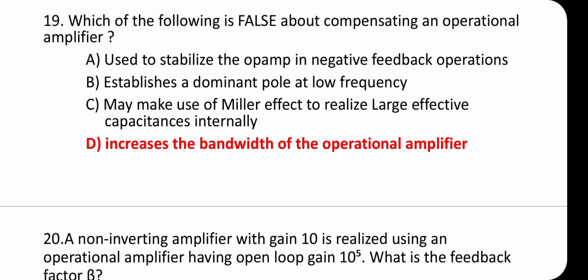Connect a large capacitor which will dominate the frequency response. The capacitor should give so much delay that the delay offered by all other capacitors is neglected. Out of the four options, D is the correct false statement, which is that it increases the bandwidth of the operational amplifier.